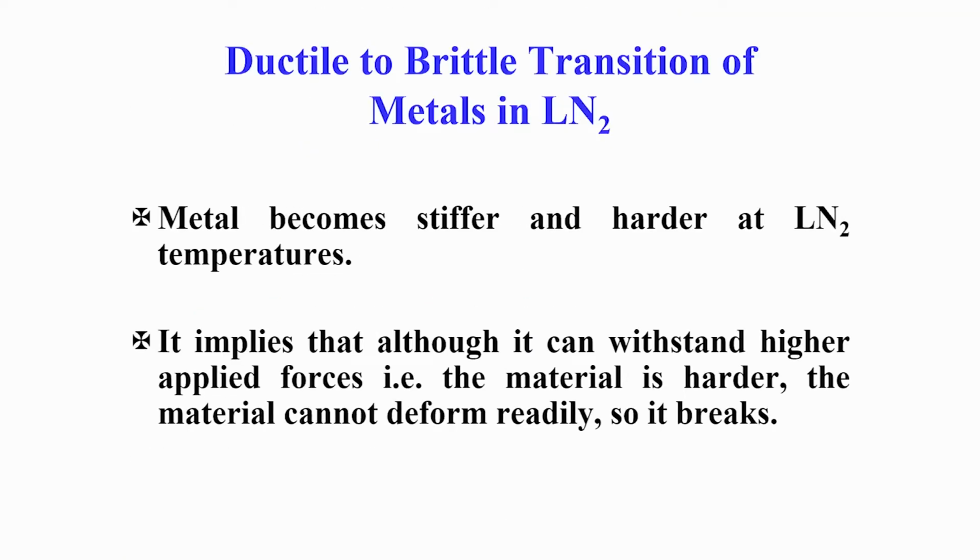One of the problems with metals is that in cryogenic conditions the metal can undergo ductile to brittle transition. This is called DBT. Those who are from a metallurgy background know that DBT leads to catastrophic failure at sub-zero temperature for many of the metals. But that certainly would not be the case for ceramic based materials, because unlike metals, they do not have a ductile to brittle transition.